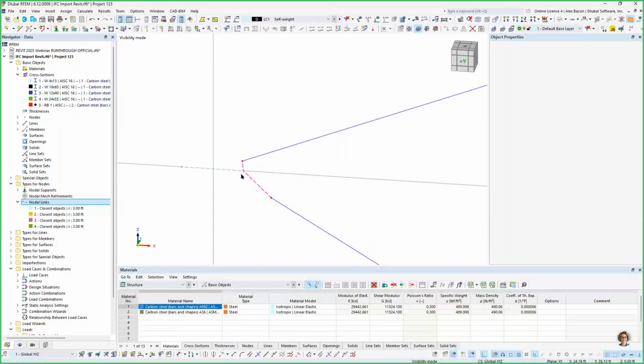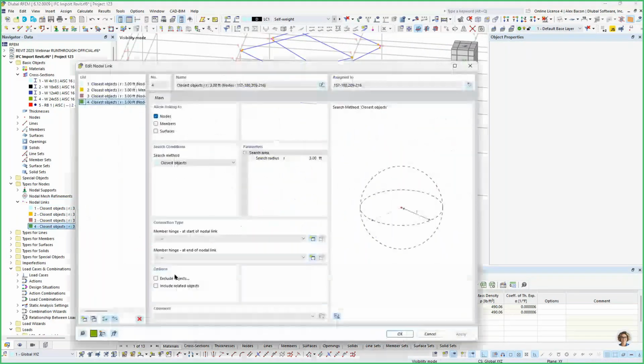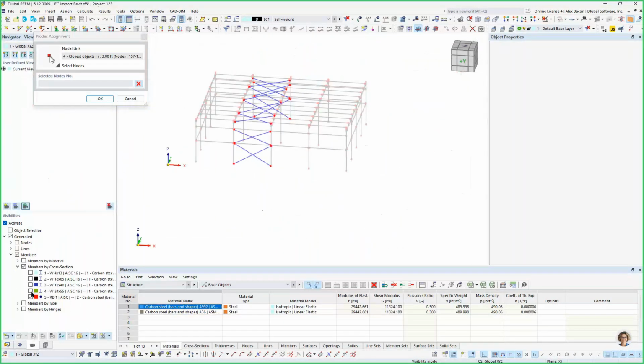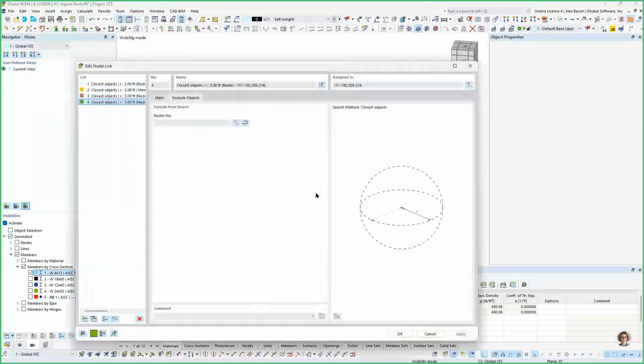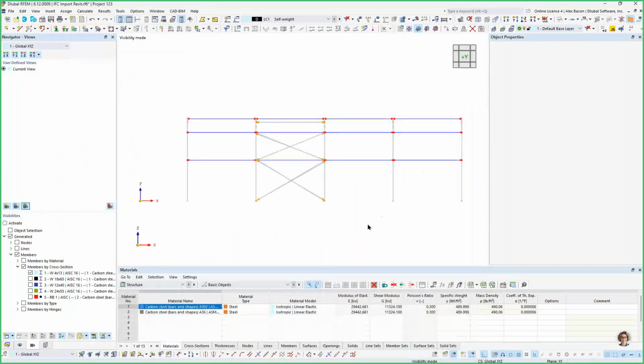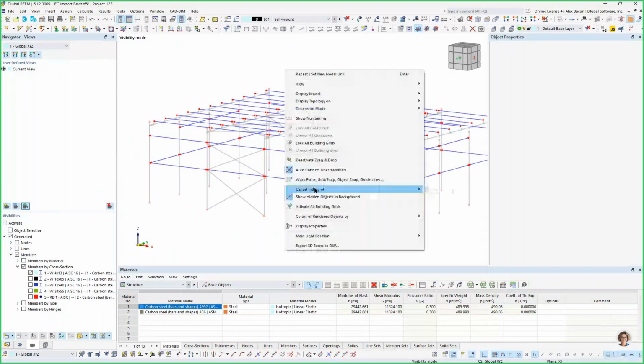And now again, we're going to have some issues with the X bracing connecting to the closest node, which is our coupling members here. So we want to exclude the coupling members now from this definition. So if I go back and I hide my cross bracing and only show my coupling members, and exclude those from the X bracing. Click OK.